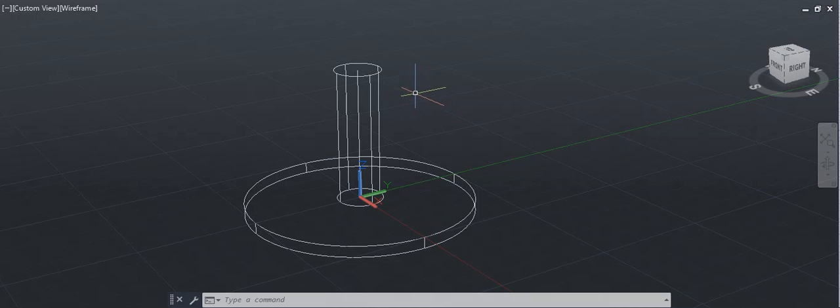That's the thing about AutoCAD you may not be so crazy about, because it does things on its own, and unless you really know what is happening, it becomes a mystery to you until you find out. So what it did is put some mysterious points on the line so that the line is divided literally into 5 equal spaces, not literally, but by just mysterious marks.